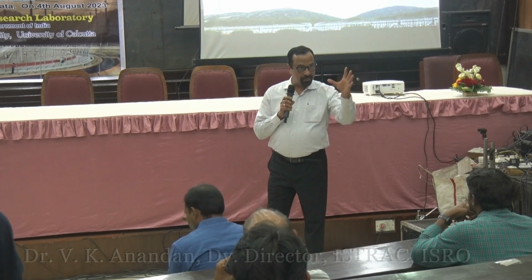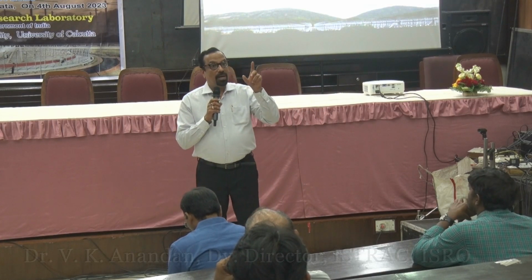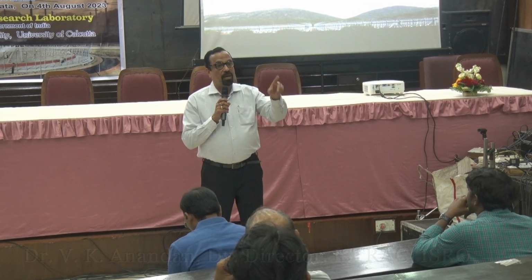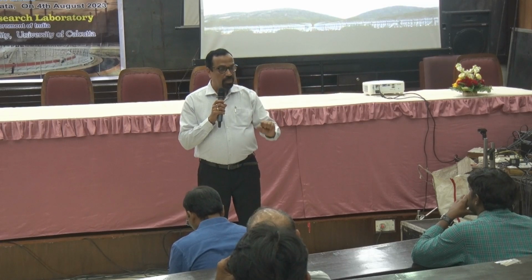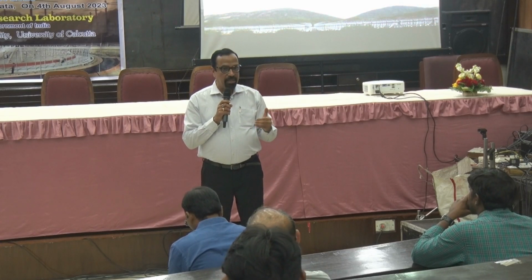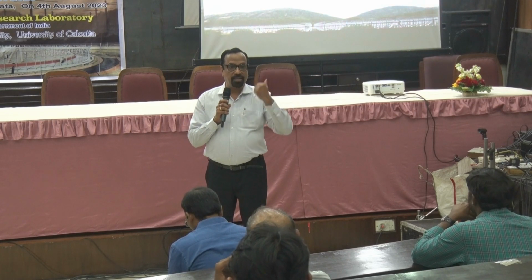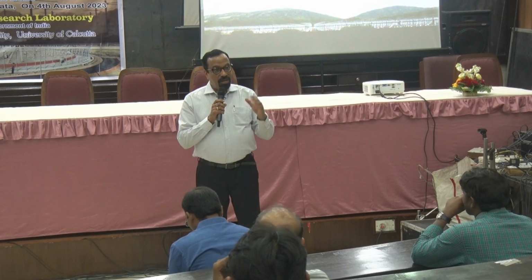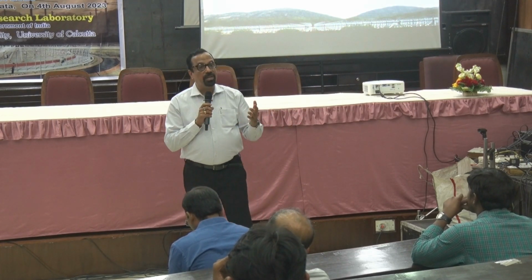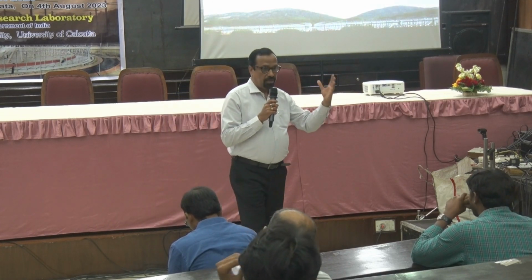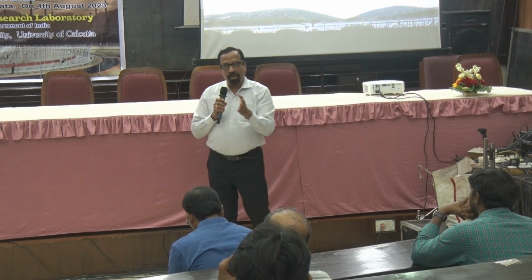Those who have studied signal processing and transfer functions, don't worry if you don't understand. But if you want to find out what is happening in the atmosphere, how do I characterize that? There is no direct method sometimes. Even if I retrieve the signal, it will not reflect what process has undergone in the atmosphere. We talk about distributions, Gaussian, Rayleigh, chi-square. When it comes to weather signals, we talk about Rayleigh, gamma, all kinds of logarithmic distributions.